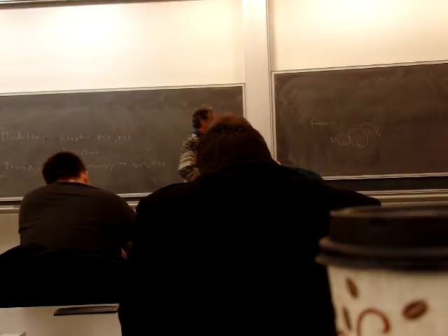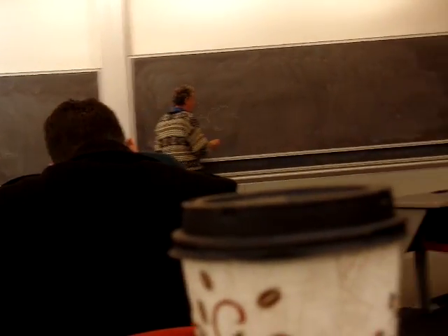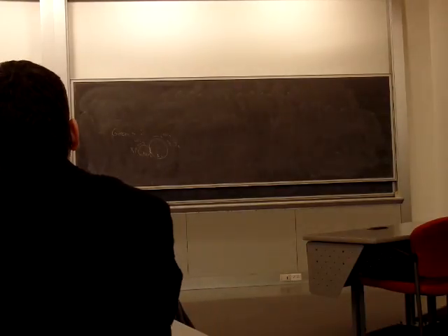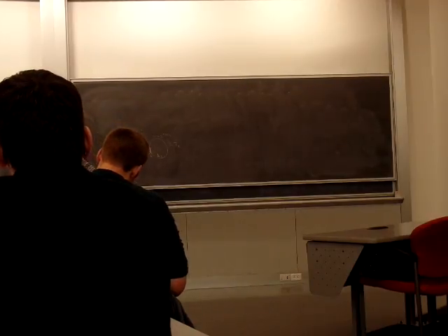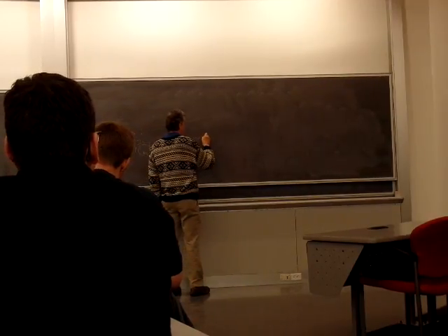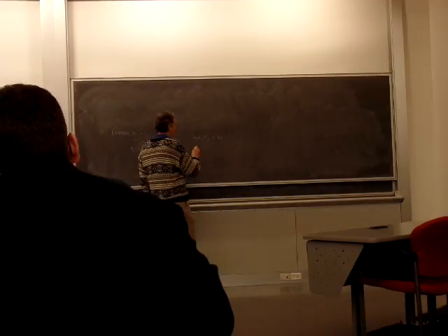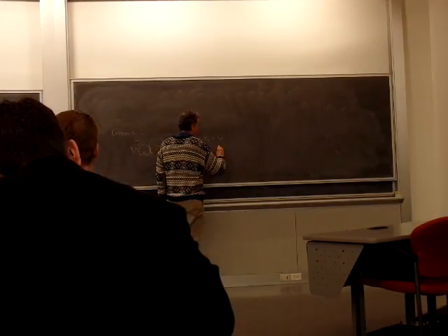So if I look at, really fundamentally here, the tangential velocity of one tooth on gear 1 and the meshing tooth on gear 2, those velocities have to be what? The same. Right? Angular velocity to linear velocity relationship is what? Omega 1 times the radius is equal to that velocity. And for omega 2, it has to be minus because of the direction.